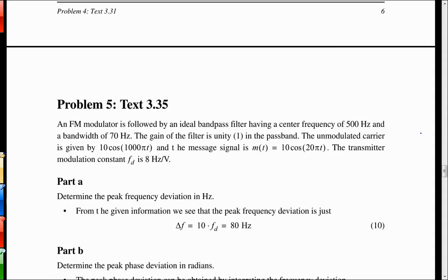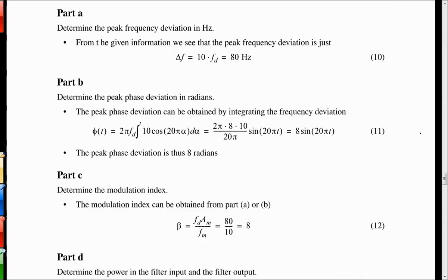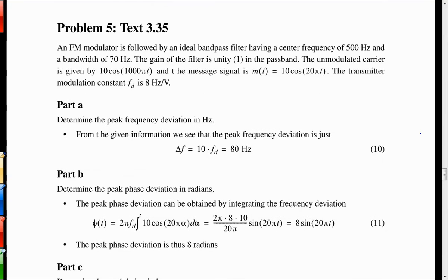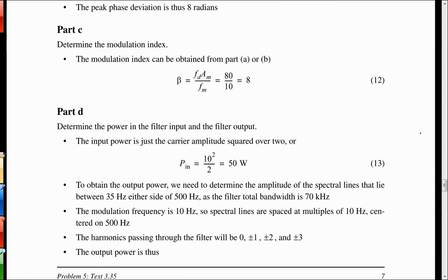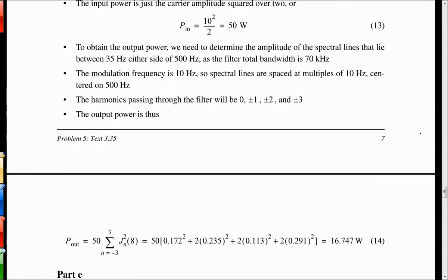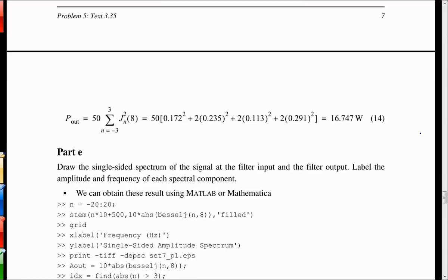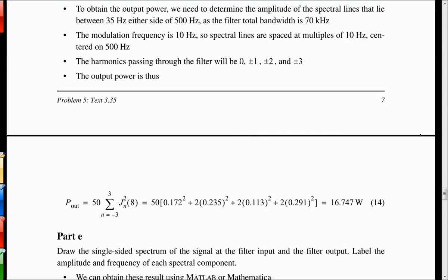So you can just look at this one as another rather similar one, except this one goes through calculations and then this one gets into a bandwidth calculation of contained bandwidth. So there's the power calculation right here. And this one was special. There was no power at the carrier, I believe. Well, actually there was. Here's the power in the carrier, and then there's 2s on each of these 3. So this had 3 sidebands on either side.